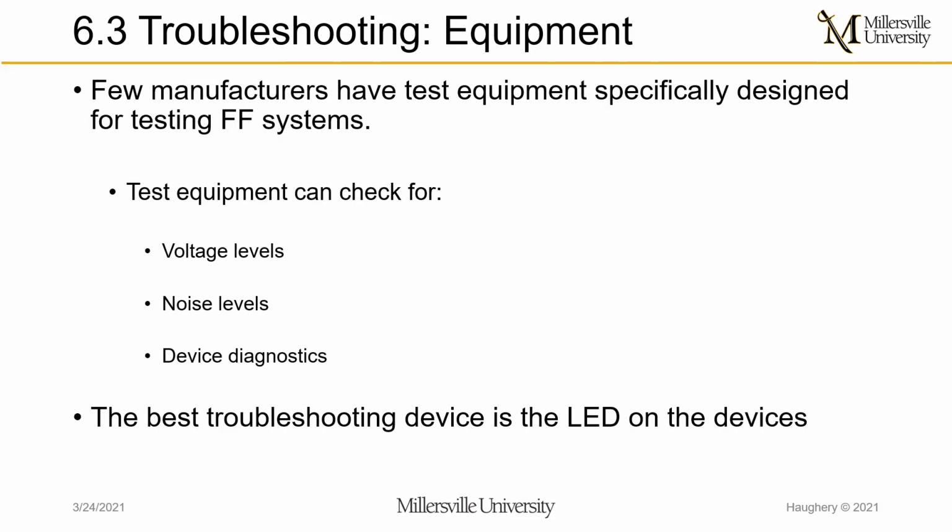To troubleshoot equipment, one can look for errors with the voltage levels on the equipment, noise levels, and also browse the device diagnostics on the network. Few manufacturers have test equipment specifically designed for testing Fieldbus systems. The best troubleshooting device is the actual LED diagnostics on the devices themselves.